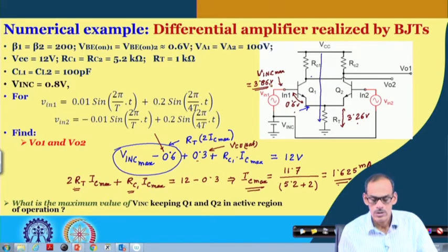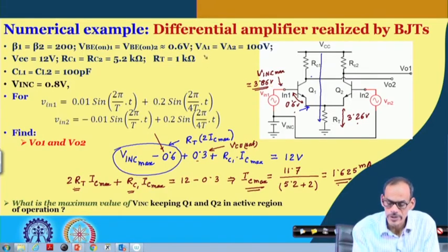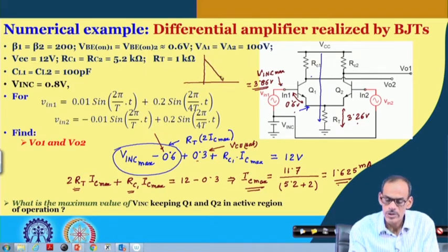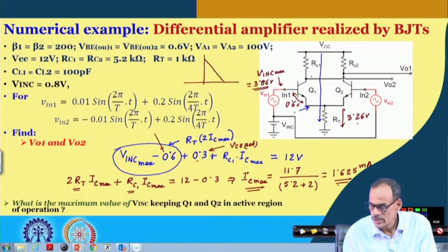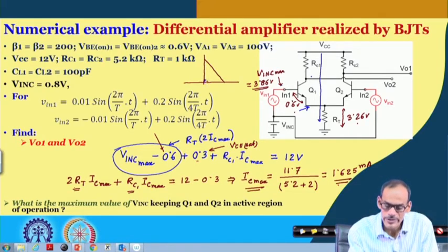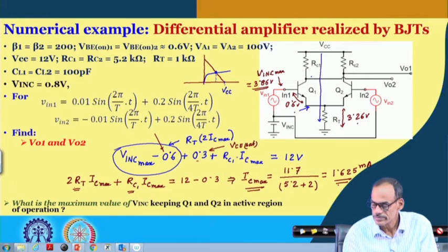Okay. So, this is indicating that if I put this limiting case, and again if we recall the load line and the operating point concept, ideally we like to keep the device in this region, and the operating point should be almost at the middle of the possible range.